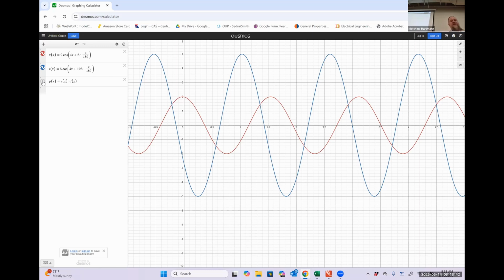What is interesting, or at least I find it really interesting, is that most of us would probably think that our average power should be just the average current times the average voltage. But if we did that, we would get an average power of 0 in every sinusoidal system. And that can't be true, because if it were true, we literally couldn't turn the lights on or anything like that. If on average, I plug a lamp into this receptacle and it absorbs 0 power, then I shouldn't see any light, right? And that would be true for any load.